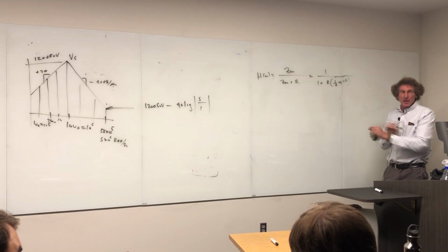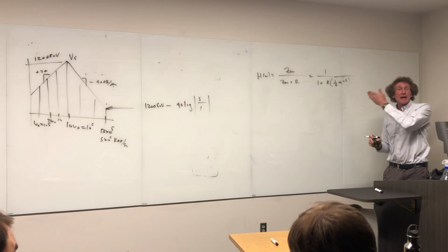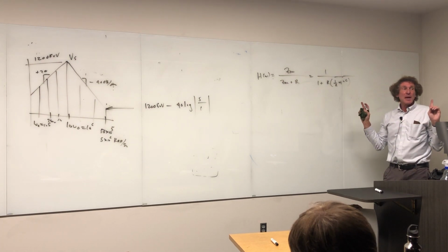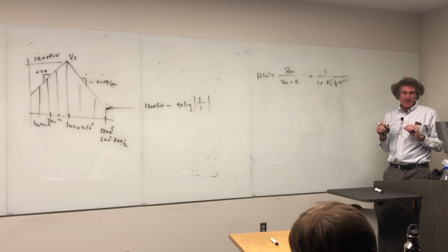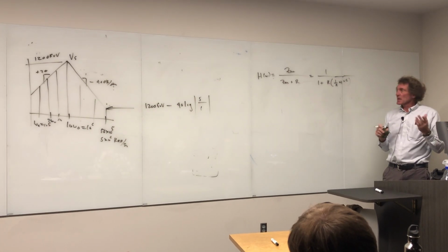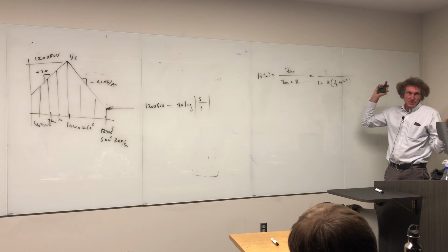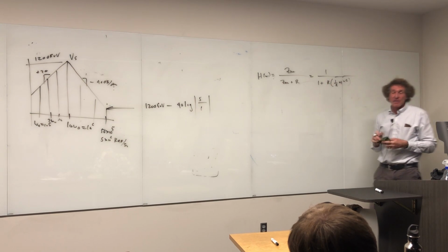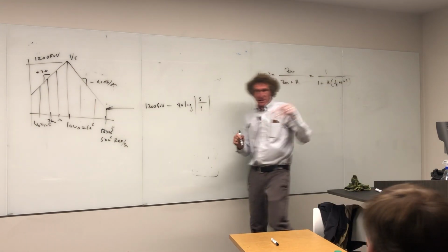I'm out of time here, but you can take 20 times the log of that with omega replaced by 5 times 10 to the 6th. Do you see that? And you're going to get a minus, because the log of 1 is just 0, and then it's minus the log of that. Evaluate at that frequency. See if you get the answer in there.